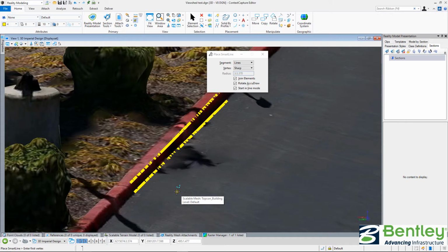Now this model here, they did use control points, so it is important that you take advantage of survey information. So many people in this industry and on this call are surveyors and engineers that have access to surveyors. If you're new to the drone world, you could start out using something like I use that has GPS in the drone to get within a couple feet and get you in the right ballpark. It's very good for a rough layout of your site. A lot of measurements are going to come out good. The coordinates are going to be within a couple feet of where they are in the real world. Relative to each other, they'll be very accurate. You'll find measuring objects and all that look very good.